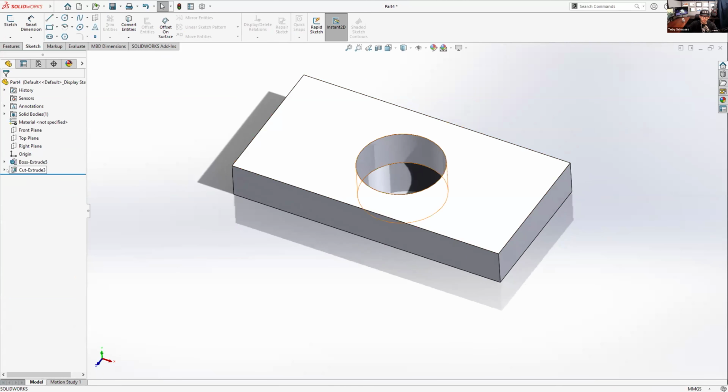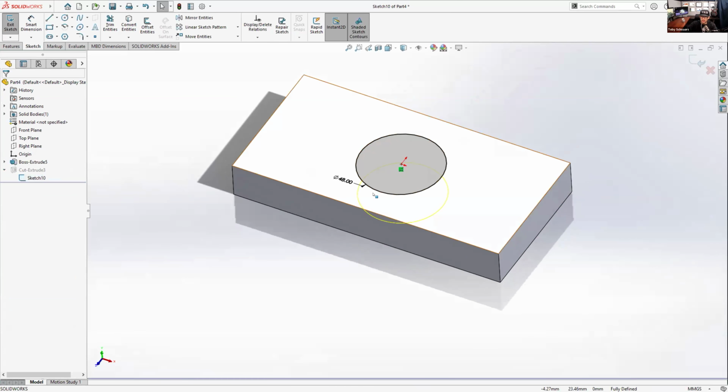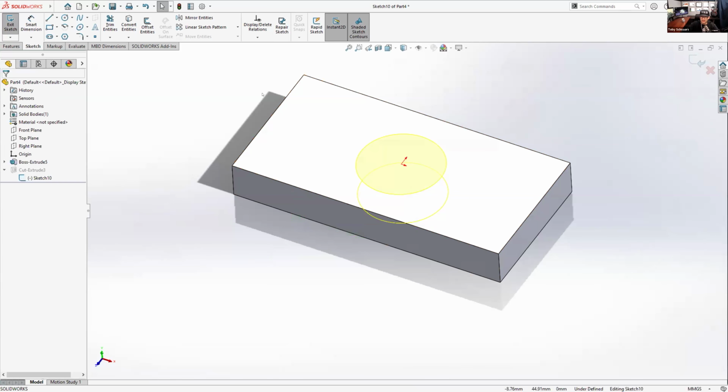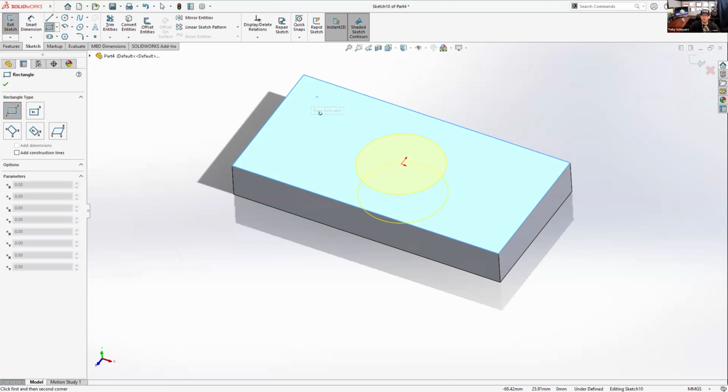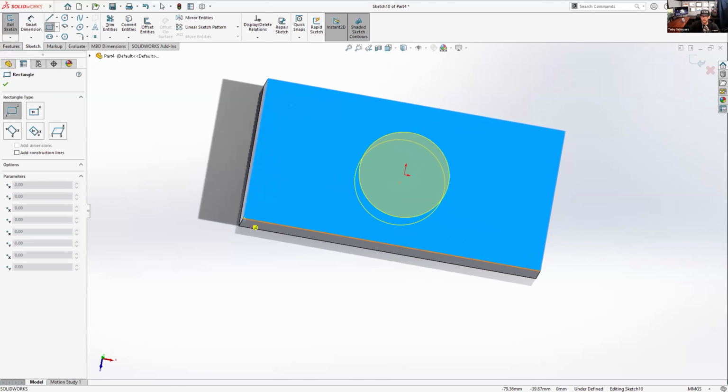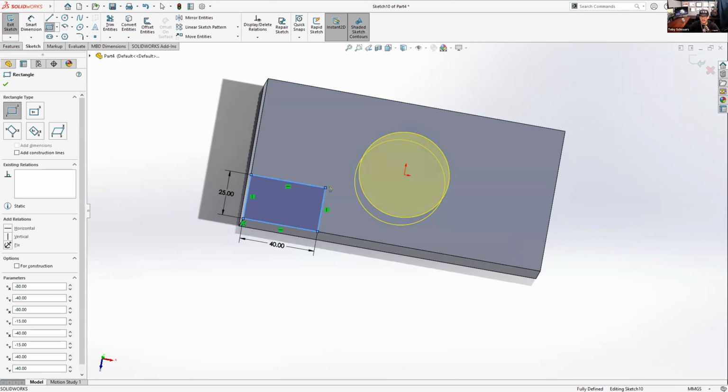And now you see we're really cooking, because as we go through and create this geometry, we're auto adding dimensions. The other thing you can do with this is stack some of this functionality, where you could do a rectangle to define the location of a hole. What I mean by that is I could create a rectangle here that starts in this lower corner and then move over like so and let go of my mouse, and I could type in 25, enter, 40, enter.